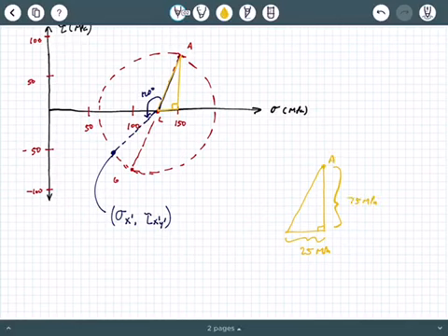If you look at this bottom value, that is 150 megapascals minus the center coordinate, which we got is 125. So that should be 25 megapascals. And then, of course, the height of this triangle is 75 megapascals because that triangle, remember, is defining point A right there. This is the center, and this coordinate, we know that. So can we get the radius from this?